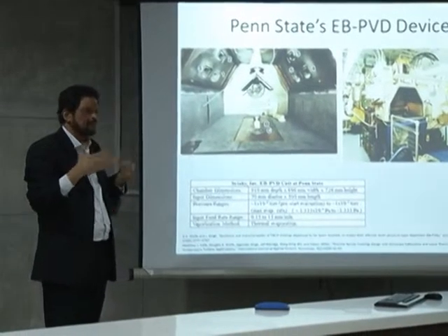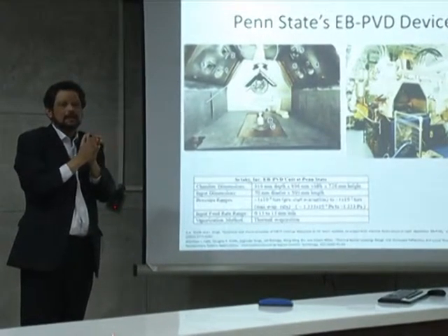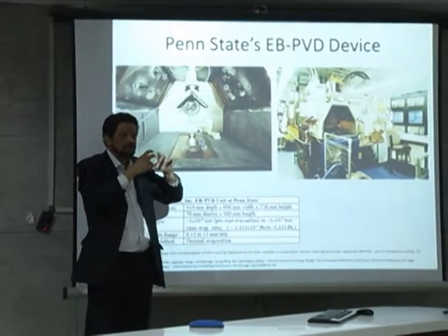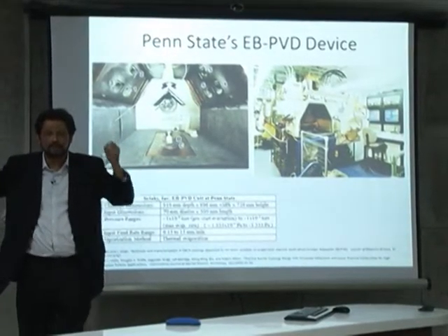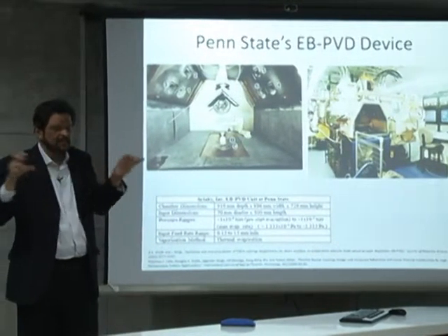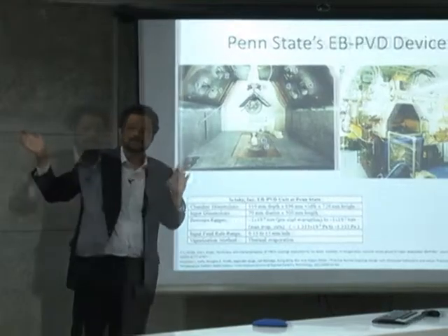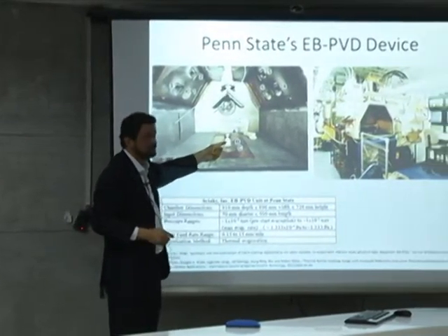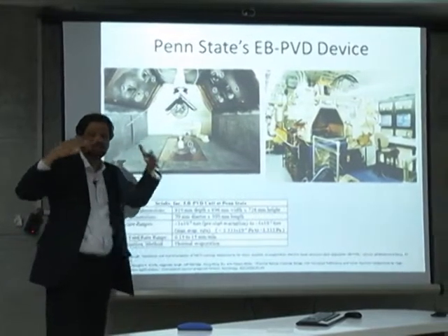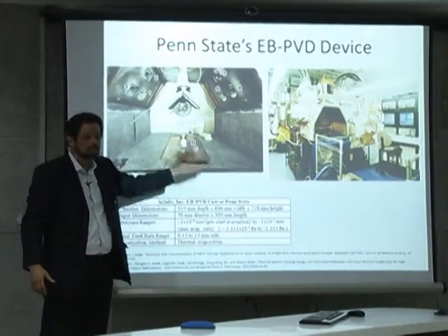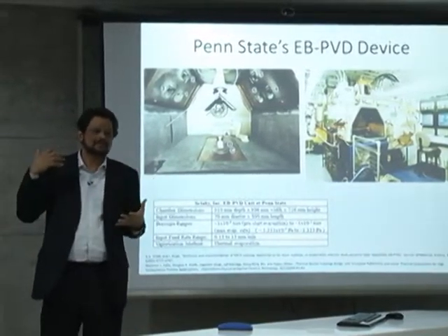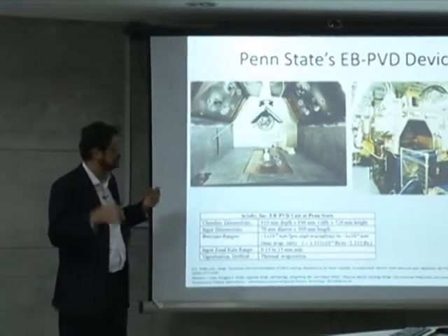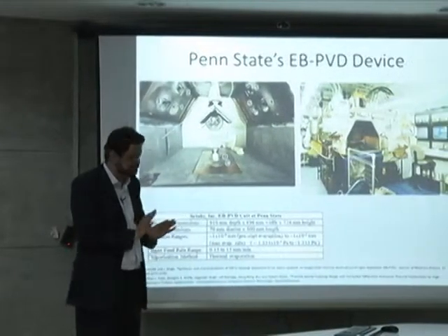So there's no question of this coming apart because it's not a simple layer. The idea is when you're done with that, we take the tube and we bake it at a very high temperature so that the carbon inside gets evaporated and goes out. So what remains is a nice tube with A inside, then B on top of it, and then C on top of it. And we can choose whatever materials we want, all kinds of molybdenum, rhenium, titanium, or even hafnium carbide, whatever. So that is the basic process.